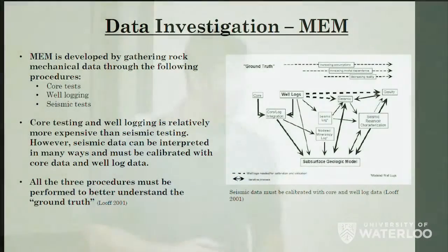There are 3 ways of gathering data for MEM, and these are core testing, well logging, and seismic tests. Well, core testing can be thought of as a magnifying glass of the geomechanical model because it takes rock information from a point in the wellbore, whereas well logging can be thought of as a glue between core testing and seismic testing because it takes rock information about 5 to 6 feet from the wellbore. And the seismic tests cover a very large area, say about 200 feet from the wellbore.